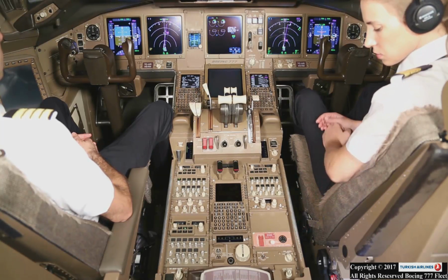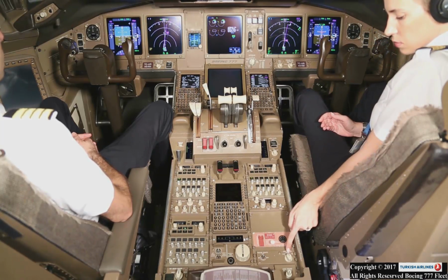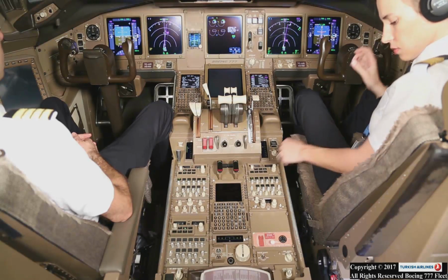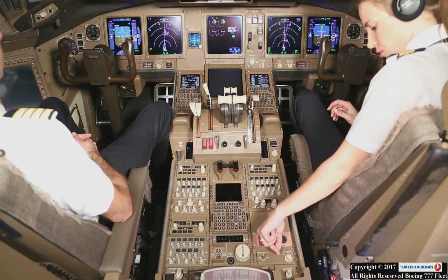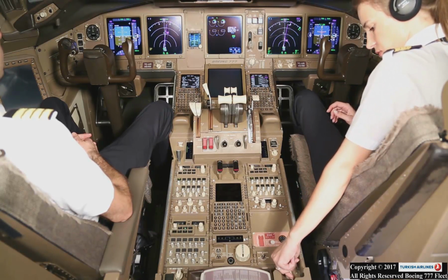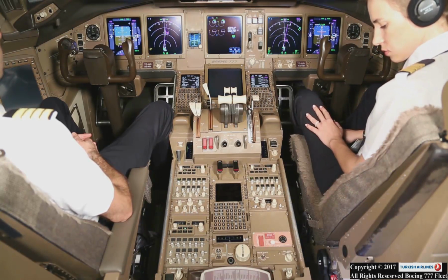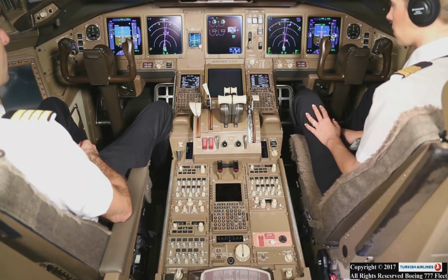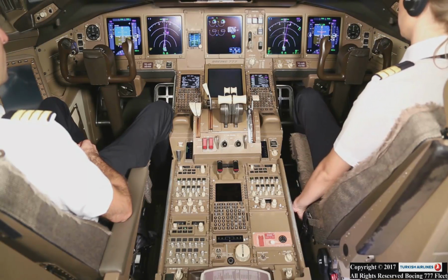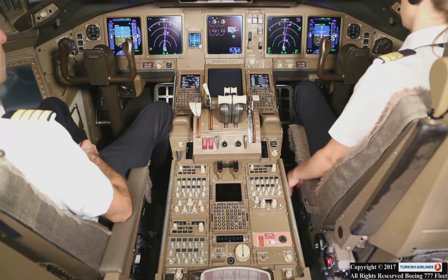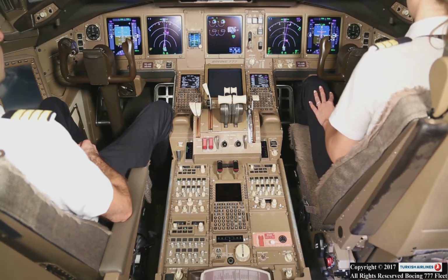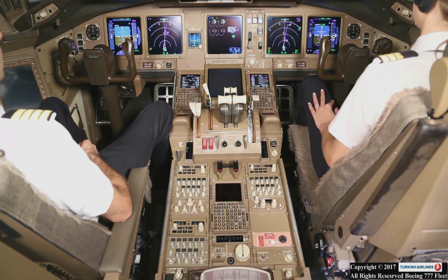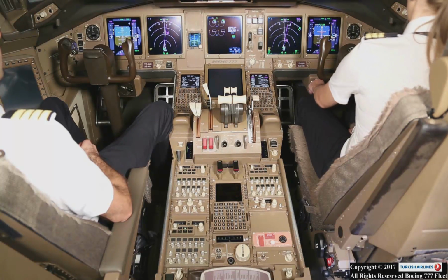Observer audio selector, north. Pedestal panel light control, mid position. Pedestal flood light control, mid position. Warning: don't put objects between the seat and the pedestal. Injury can occur when the seat is adjusted. Seat, adjust. Adjust the seat for optimum eye reference. Whenever the seat is adjusted, verify a positive horizontal fore and aft seat lock by pushing against the seat.